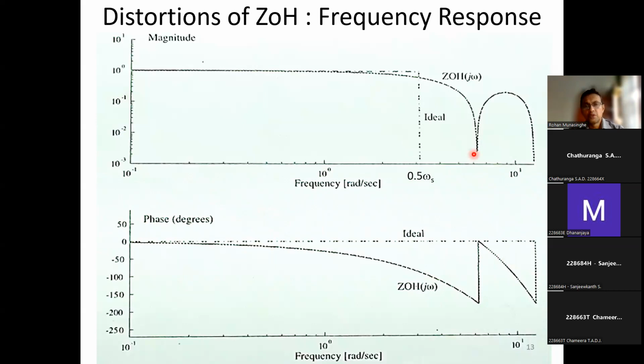All right. So the zero order hold circuit is a bit more complicated than you would have initially thought. You probably thought it takes the samples, that's it. But actually, it's doing a little more than that. It deteriorates the frequency spectrum. Now, if you design your system so that you stay here, this is half of the sampling frequency. The sampling frequency is something you can design arbitrarily, whether it is 20 or 200, it is all your choice.